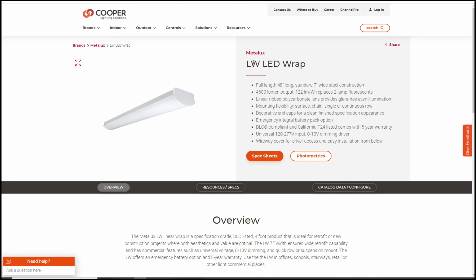The other sort of light I was looking at is basically what I have in the space right now, which is an LED troffer, kind of mimics a 4-foot fluorescent, the old style. This one here, specifically the Halo fixture, has a 4600 lumen output, and it's meant to be a replacement for fluorescent. Some other things here are that it can be dimmed, but it's pretty simple. These tend to be LED, and you can get them in a couple of different color temperatures.